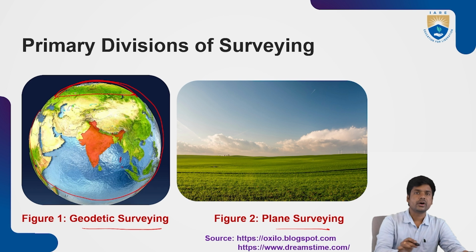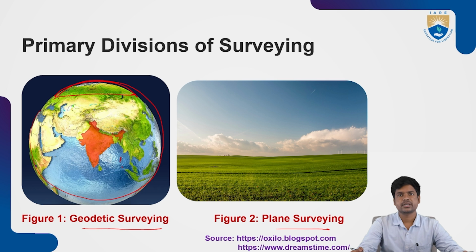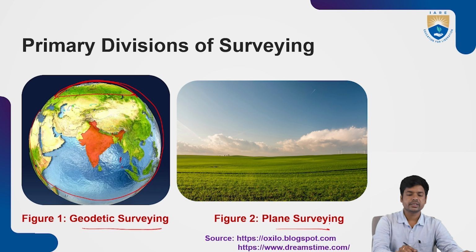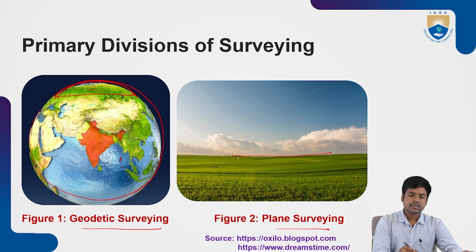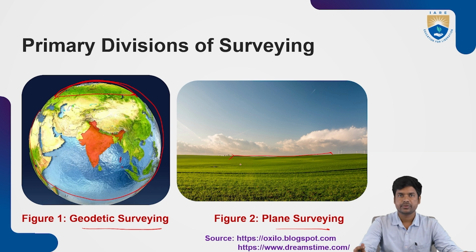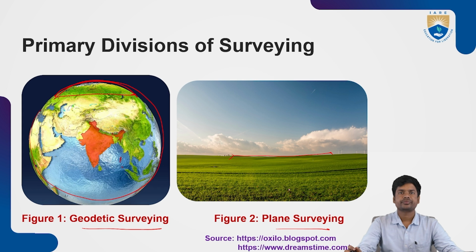Whenever you have large areas, wherever the curvature is going to affect the measurements, then you go with the geodetic surveying. And coming to the plane surveying, here the earth curvature is not considered. So the earth surface will be considered as a plane surface. The effect of this curvature is very minimal. Whenever the area is very short, the curvature effect will be very minimal, so we are going to neglect the curvature of the earth. So these are the two different types of survey.